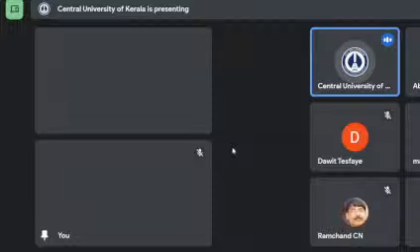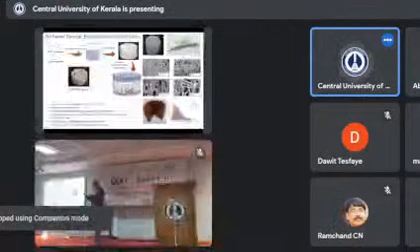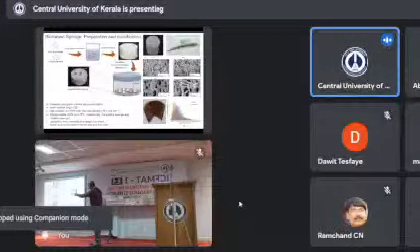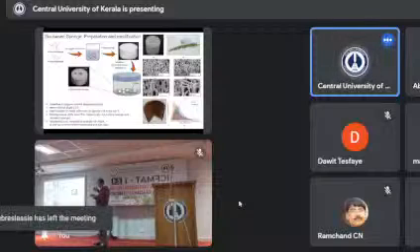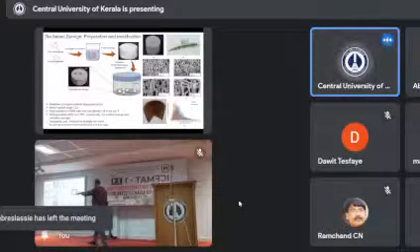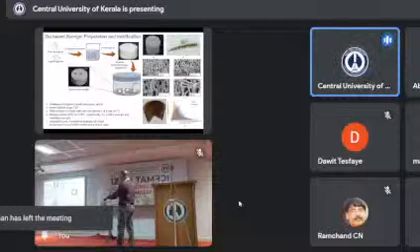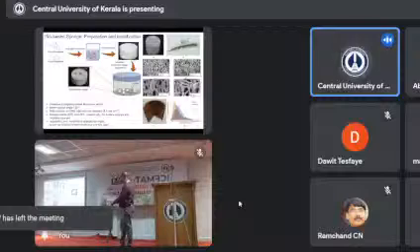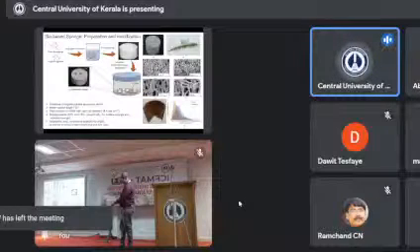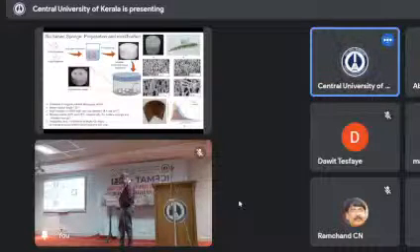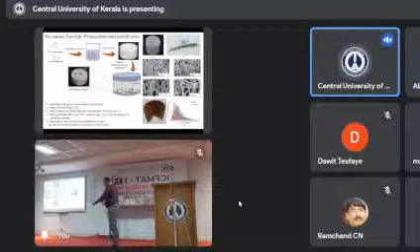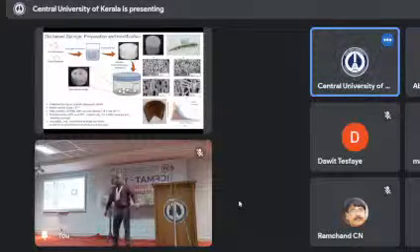Next I want to show how we make the sponges. We have made different sponges by using a combination of two gums, just by the freeze drying method. These two polymer solutions can make a sponge, and you do the silylation, so then you can make a hydrophobic sponge. What is the advantage of this sponge? The water contact angle is 130 degrees, and they are highly porous in nature and have very low density. Density is 18.4 milligram per centimeter cube.